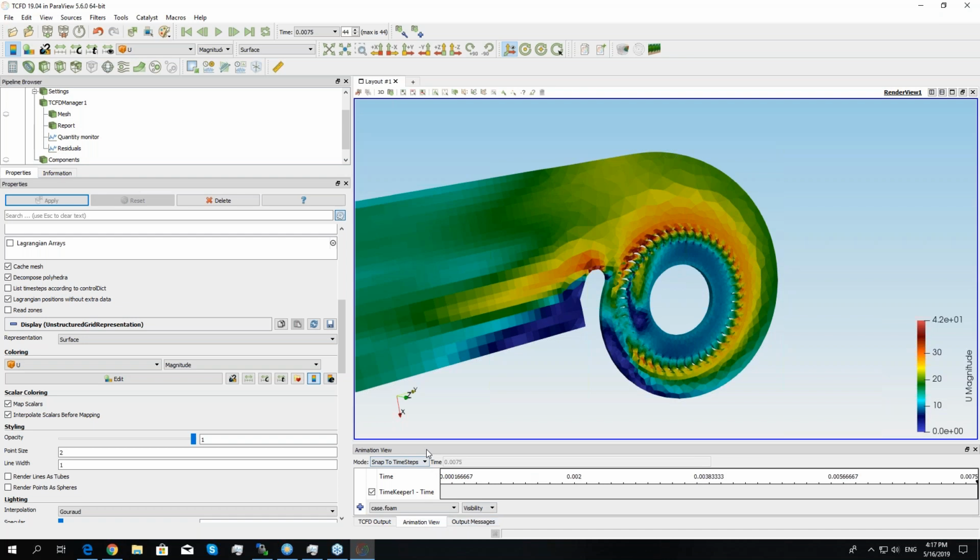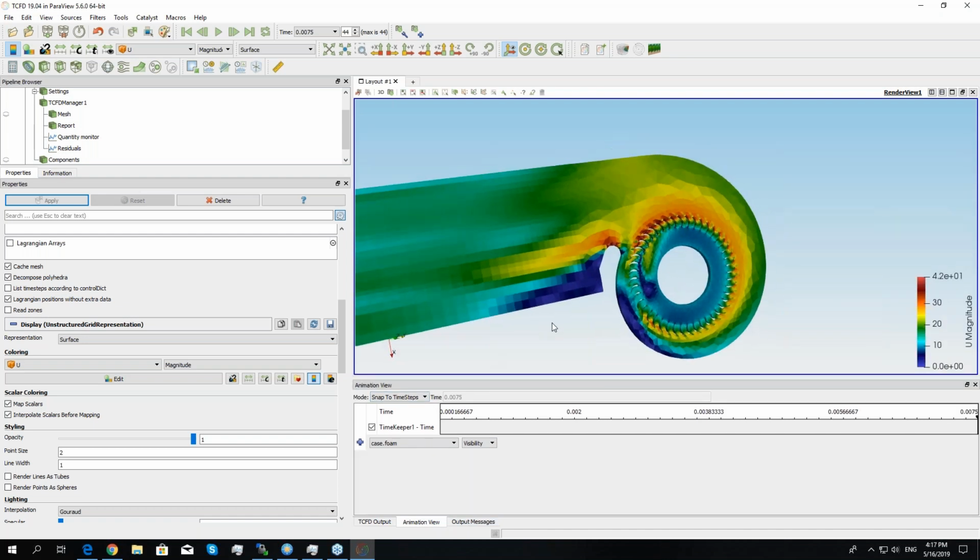This is the animation view in which you can play with adjusting any parameter of the simulation, visibility and so on. But what I would like to show you is to adjust the camera. So you can go for the camera, and there are many options for how to adjust it, to have the orbit or define a path along which the camera will go.